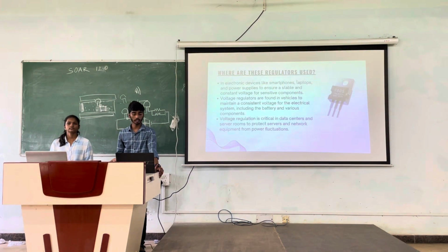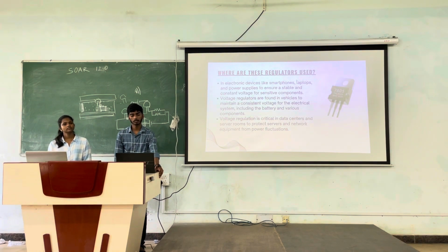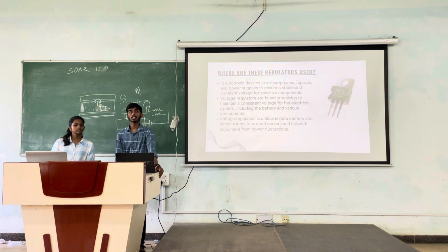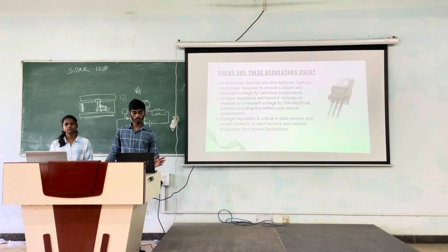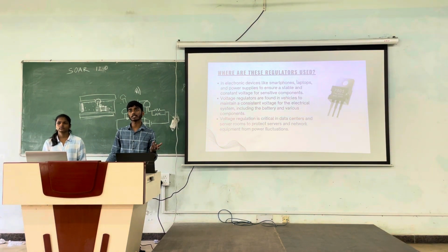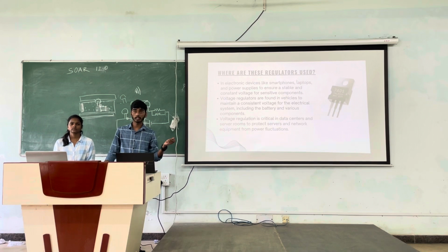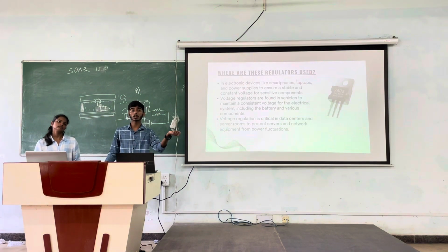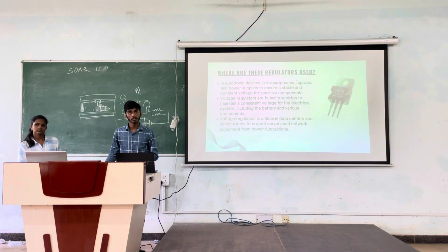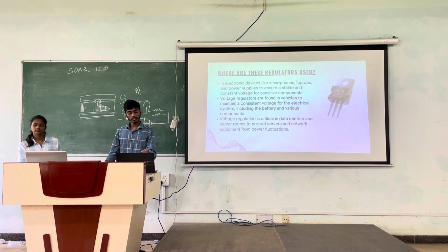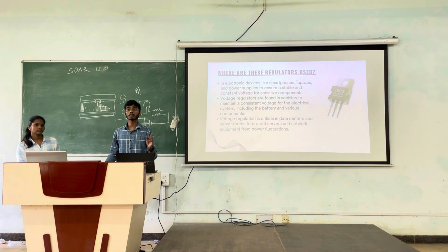One more thing that we see in our vehicles: we have batteries. What if we speed up our car, and our car has a dynamo system? The dynamo generates voltage, and the power delivered by this dynamo is used to charge up the battery. So voltage regulators are used in vehicles for this purpose also.